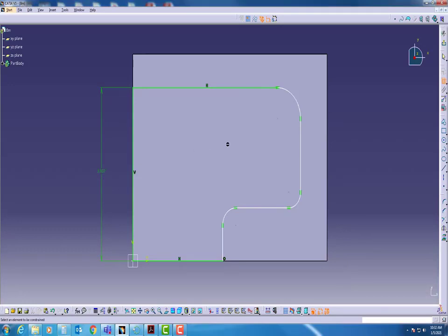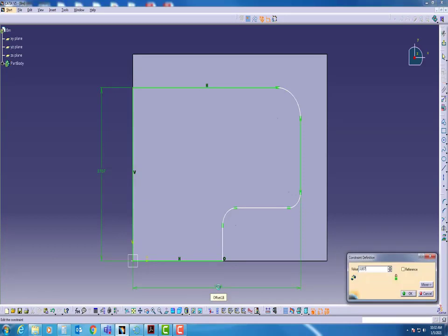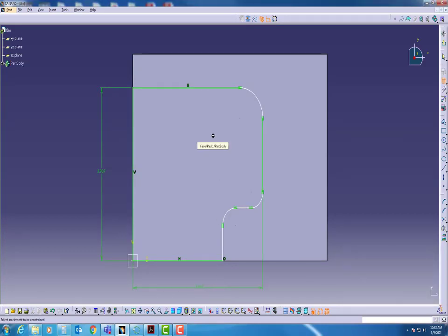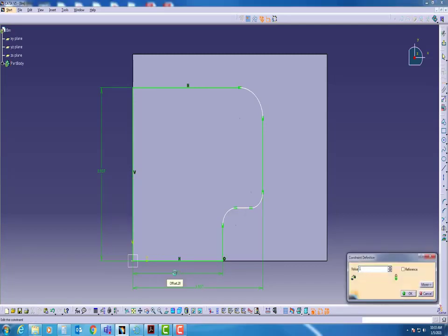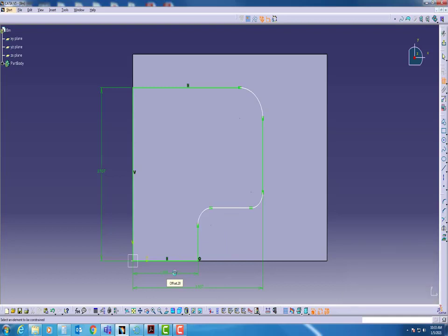And then I'll do the same thing for the next one. If I want to dimension all the way, I'll click from here to this line, and it is also the same amount. It is going to be 3 inches 937 thousandths. So now it's starting to look a little bit better. Now I'll constrain this bottom area to right here, and that is going to be 1 inch 969 thousandths. And what I'll do is just come back through, and now that I've got all my lines constrained this way, I'll start constraining the height, which is the last one, which is right here.